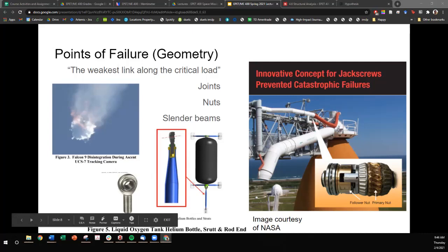More than 4,000 jack screws were in use around Kennedy Space Center during the space shuttle era. NASA used some of these jack screws on critical hardware. Thus, a fail-safe, continue-to-operate design was needed to mitigate the possibility of a catastrophic event in case of failure. A conventional jack screw contained only one nut made of a material softer than that of the threaded shaft. With prolonged use, the threads in the nut would wear away.